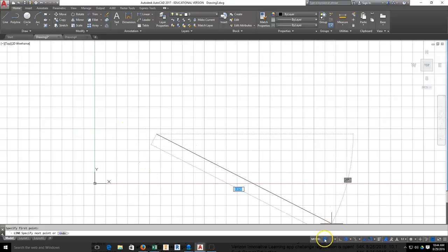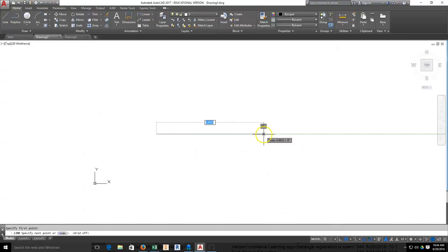Now I'm going to come down and turn off my grid so it's a little less cluttered and you can see what's happening here a little bit easier. So just want you to move around and take note of the tools that are popping up for you. If you hit tab, it toggles between the length and the angle. So you could input a specific angle, toggle back to do a specific distance. Okay? So for now, what I'd like you to do is pulling out on the 0 angle, I'd like you to type in the distance of 5 and then hit enter.